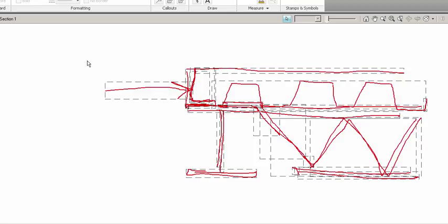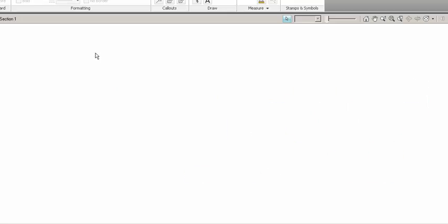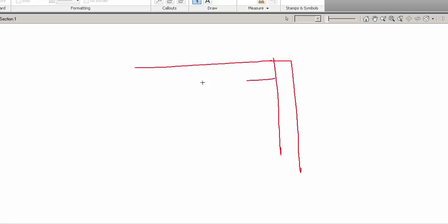So we can use them as struts, we can use them as kickers, obviously we can use them for all kinds of different things. Now in a set of plans, if we were to go back to that little detail I had right there: steel column, steel beam, kicker member, shear clip right there, drill a bolt hole in the angle to match up.